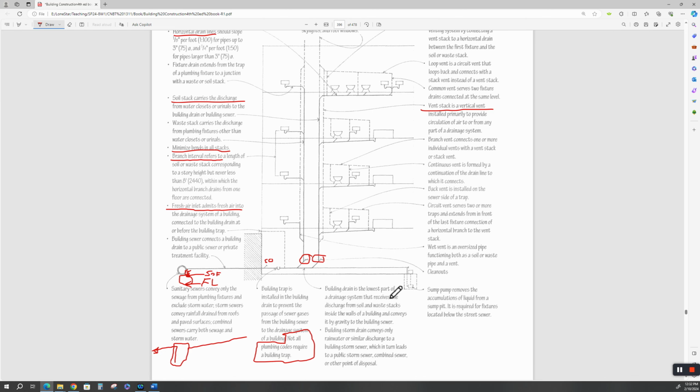And sometimes in some remodeling jobs, let's say you had a basement in a house, and you wanted to put an apartment down in your basement, you might have to cut a sump. So you could put a toilet in here, or a bathroom or something, and you got to size the sump and the float switches and everything else to lift all that up to the sewer of the house. All right, well, that's what a sump pump does. Okay, and as you can see, you got a clean out here, which is a nice run all the way down here, and we got a clean out there and a clean out there. Do not skimp on clean outs.